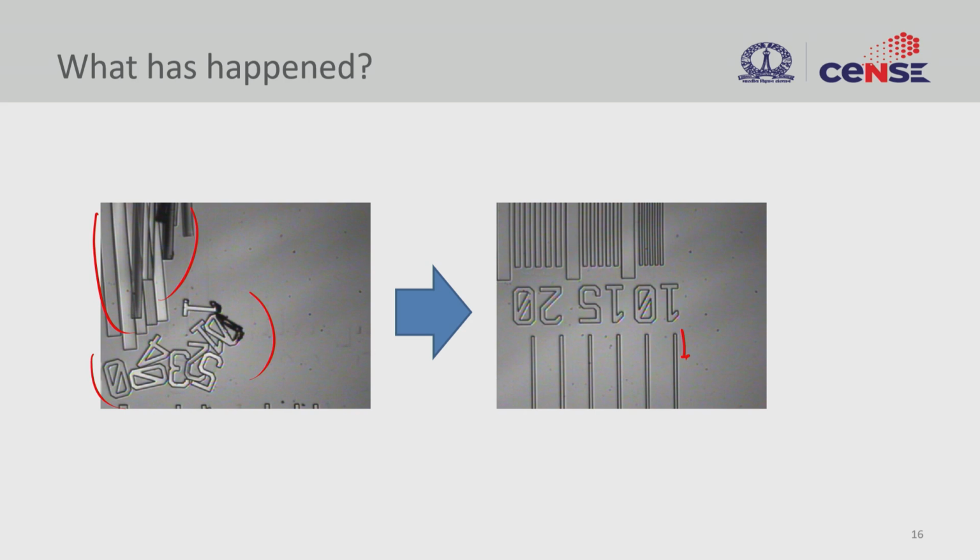Some of you who have done fabrication can quickly recognize that here the patterns are nicely fixed onto the substrate or the coating that we have given, but here they are all floated. You have nice features, and the lines are also very nicely done, but they are all washed away. So this is a problem of adhesion.